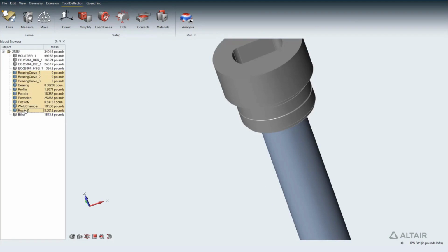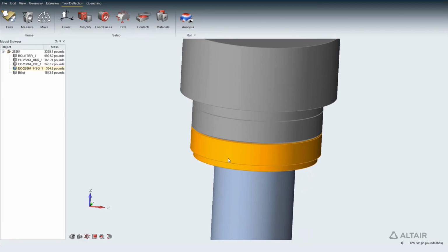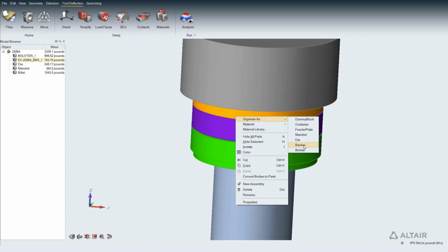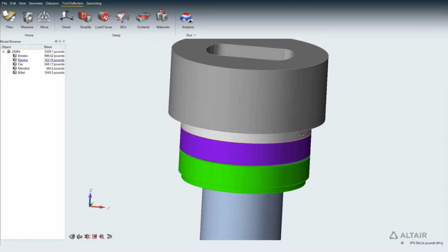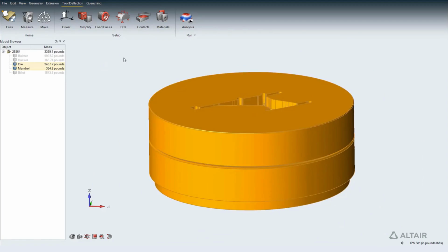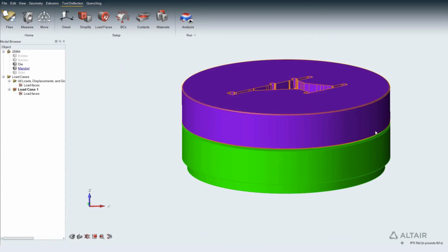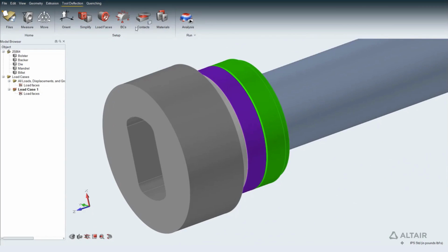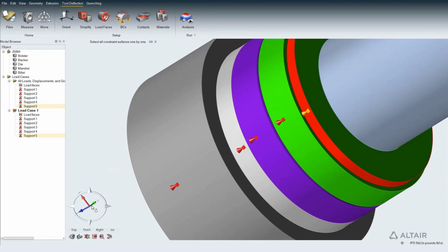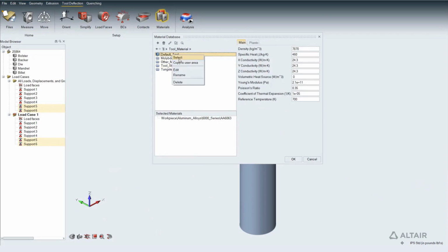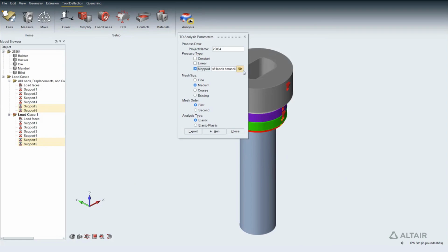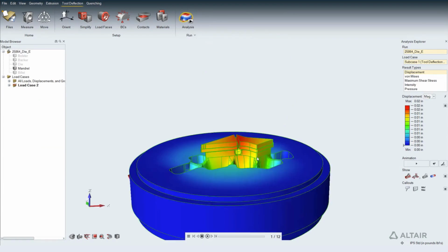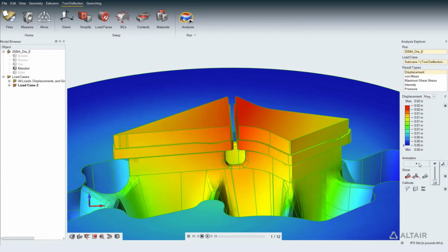Tool deflection analysis determines where and how the tool is likely to deform during the extrusion process. It also helps the die designer to make corrections in the tool components accordingly. Inspire Extrude provides three different ways to perform tool deflection analysis, either through coupled flow, thermal and stress analysis, or by writing a FEM file that contains tool mesh, material data, and BCs, which can be submitted to the OptiStruct solver for stress analysis. In both cases, the model should contain both the workpiece and the tool components. Tool deflection analysis can also be done using the analysis wizard in Inspire Extrude.